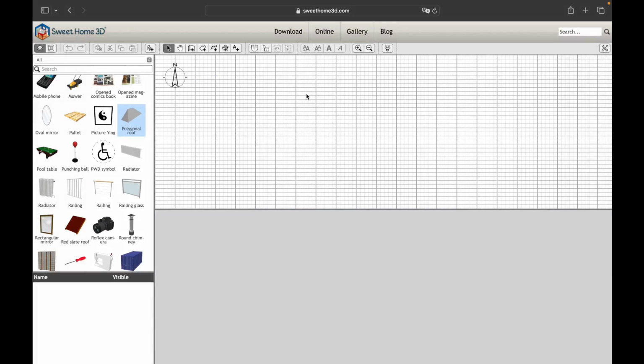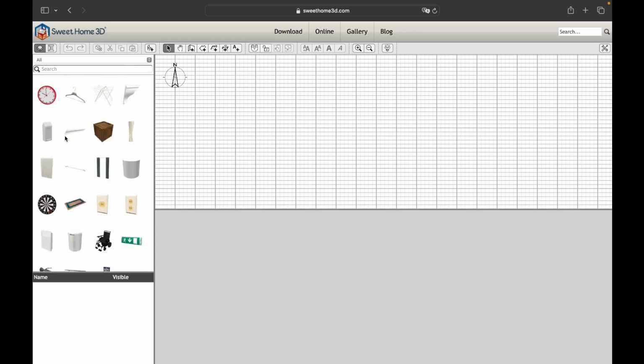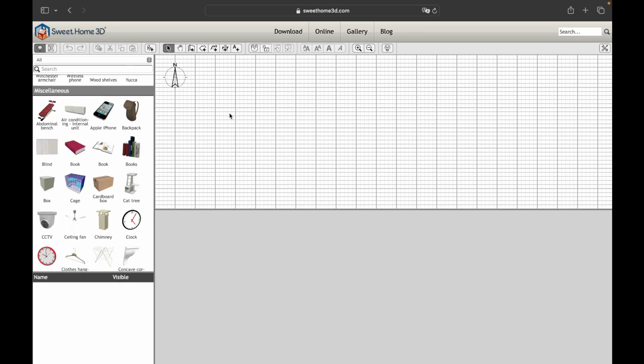We now have a general but complete overview of the interface, tools and commands of the software, but obviously each tool will then be explored specifically in the subsequent dedicated lessons. In fact, this lesson will focus on one of the basic but essential tools for the creation of a building, the walls. To begin, we select the Create Walls command on the toolbar.